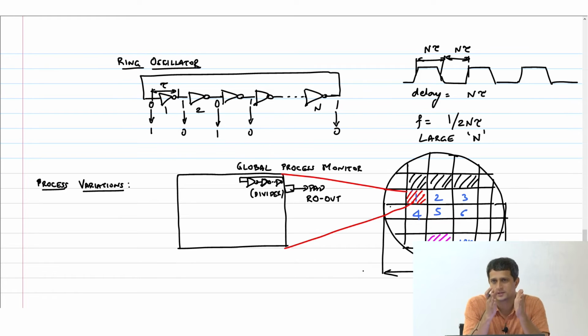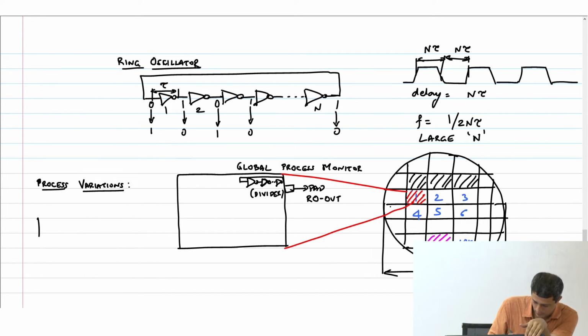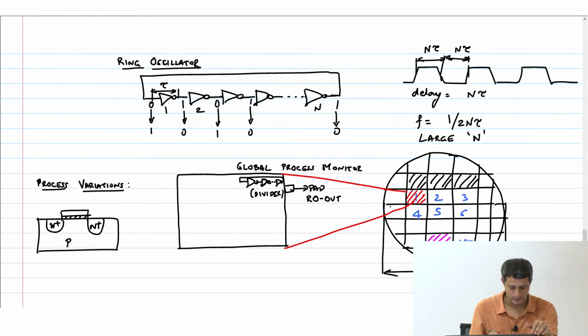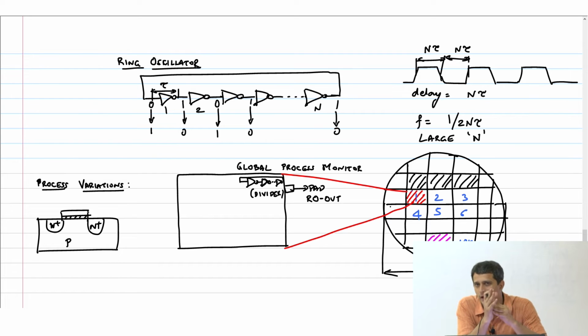So you take a transistor, and this is my gate, N plus, P, oxide thickness and all that, right? So first of all, we are now trying to manufacture physical dimensions of what order of magnitude? 14 nanometer, 20 nanometer and so on. Unfortunately, the wavelength of light that is used to do this process of lithography is 192 nanometer.